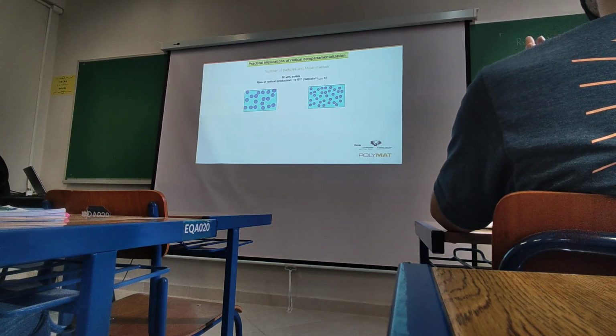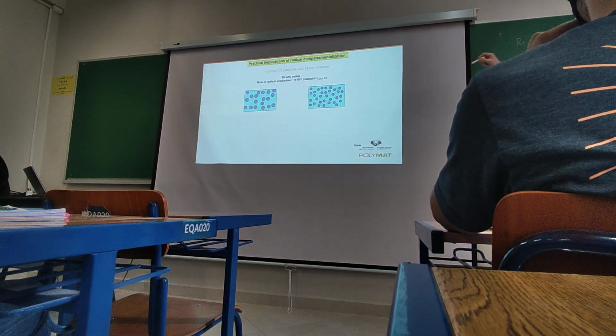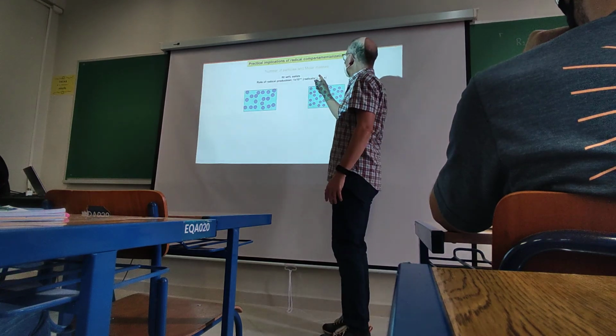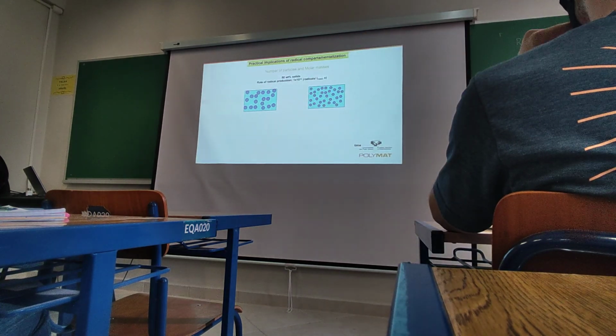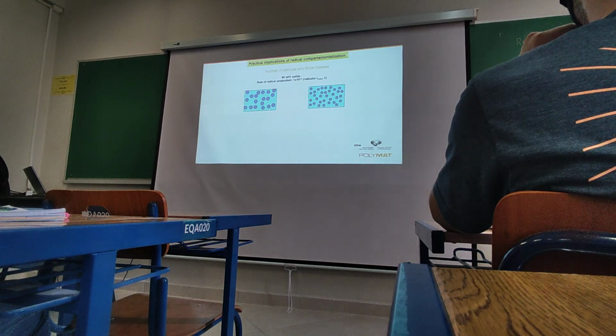Okay, if you assume normal constants for the kd and for the concentration of initiator, and you multiply by Avogadro's number to have radicals per liter of latex per second, you get more or less this value. Assuming that this is 0.6, I think that I use this rate for kd, and I think that I use a normal concentration for the initiator, which are normal concentrations.